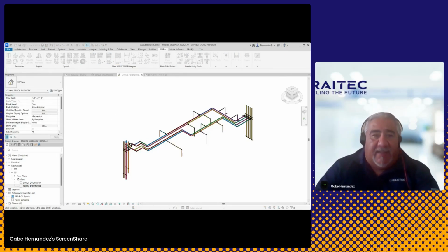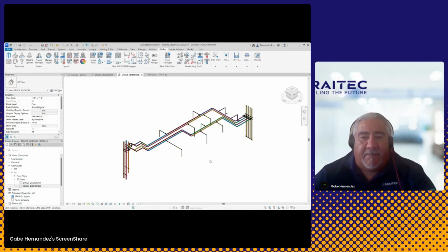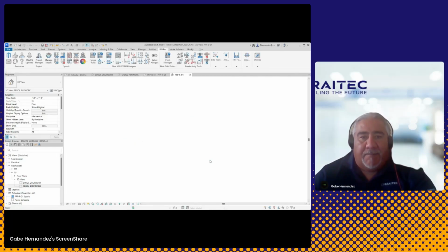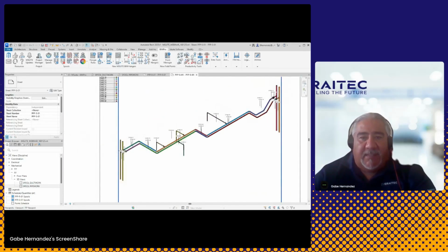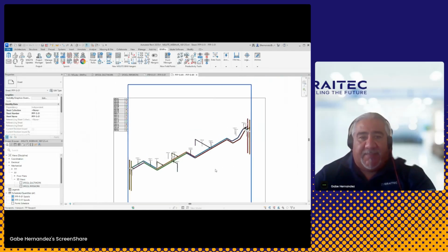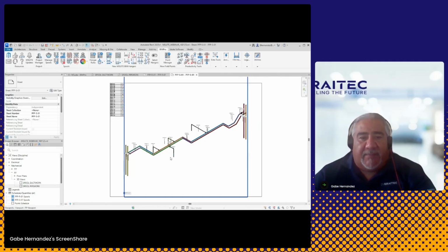Supply, and then prefab package, supply 01, create. And there you go. Now I've got my spools. Again, you can use whatever custom tags you may want. Maybe not put leaders. Maybe put the bubble tags that are inline. But you still, again, may need to make some adjustments here. But now I've got that printed out.